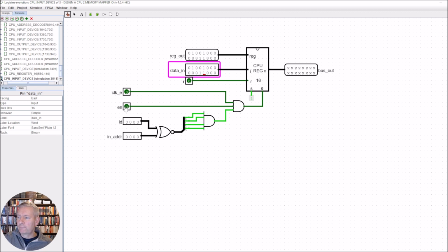This is going to come from our address decoder, and it's going to tell us it's a memory input output. So we've chosen a memory input output. Secondly, we have to choose which memory input output, because there's going to be 16 of them. And again, this is a neat little section here that was generated by Timothy Morgan. So thanks again, Timothy, because this is another brilliant little bit of circuitry.